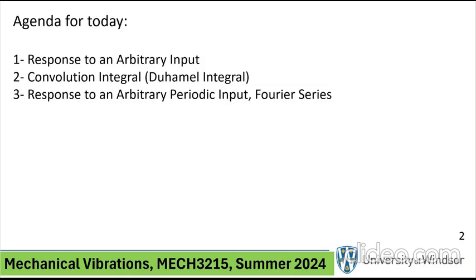Now, in the last lecture, I said, why don't we, instead of taking a harmonic force, take a very special type of force, which is a force that is alive over a short duration. Obviously, maybe before that duration the force was not there. After that duration of interest, the force is not there, it's 0. But during that short interval, there is a forcing that starts from 0, goes to some maximum, and then drops down to 0. We call that an impulsive force, okay? A short duration force. Now the word short duration by itself is a loaded word: short with respect to what? That was actually brought up in the last lecture. But anyway, let's move on.